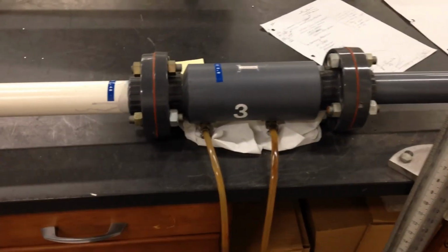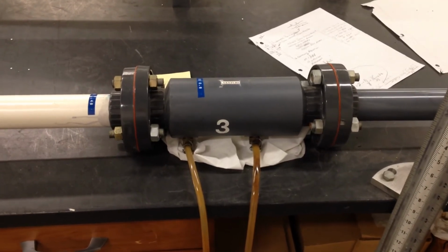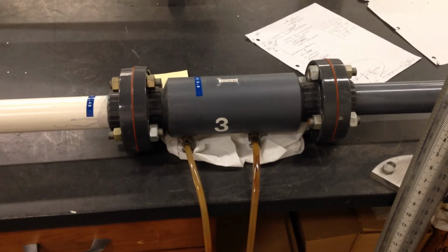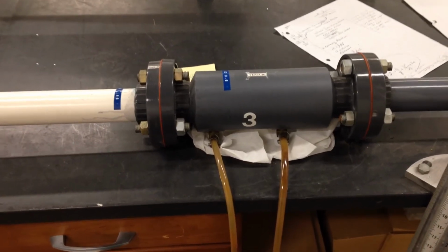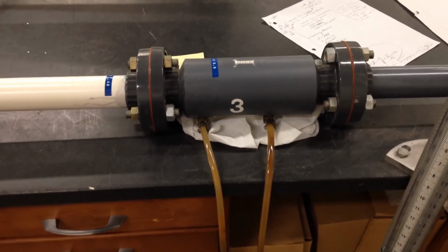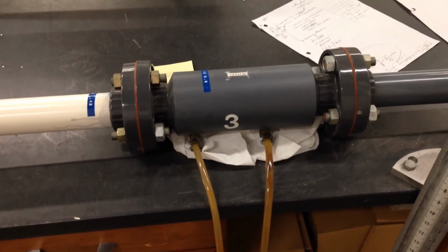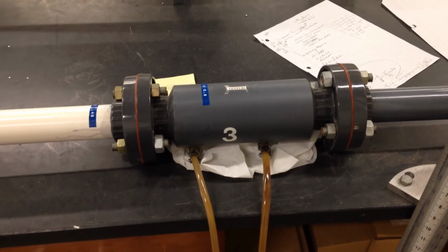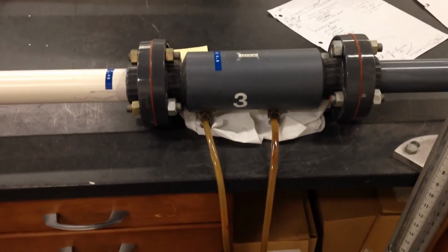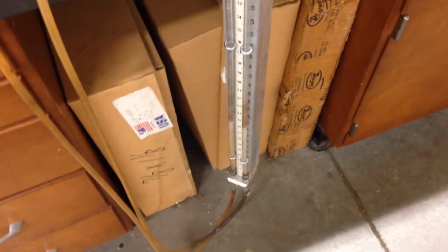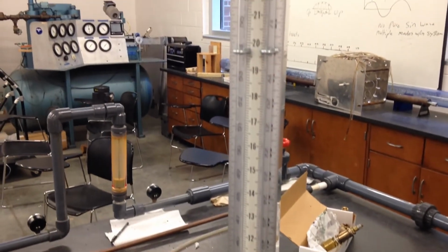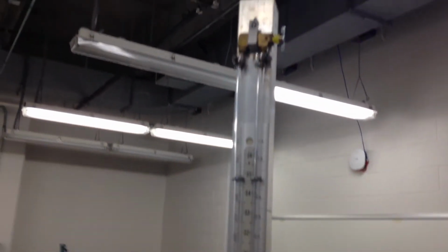Okay, moving right along, we have the Venturi. Notice that one of the big differences between a Venturi and the others is that it takes up more real estate. The Venturi has a much more gradual transition down to its throat diameter, and as a result takes up more real estate. If you have the real estate, obviously a Venturi is more efficient. If you don't have the real estate, then you're obviously going to use something else. So that's a classic type of trade-off. And it has very direct tubes to its manometer.